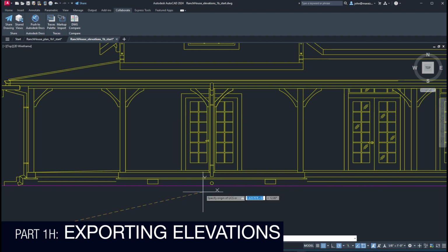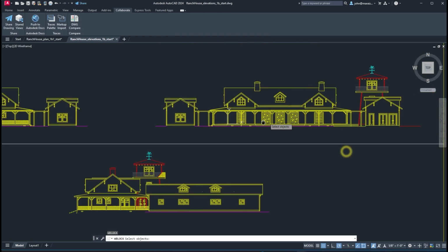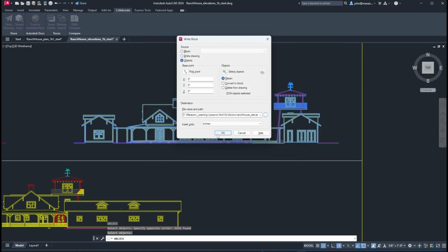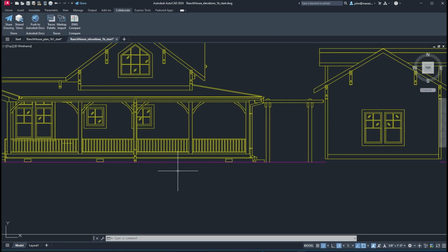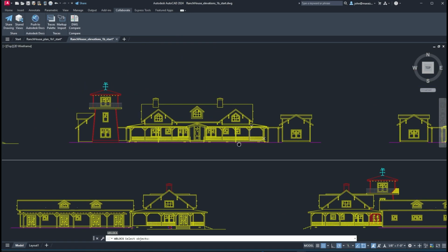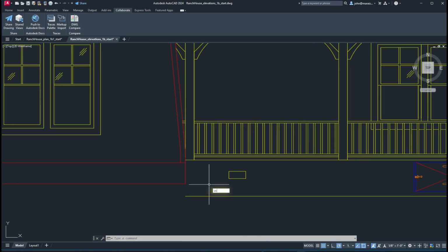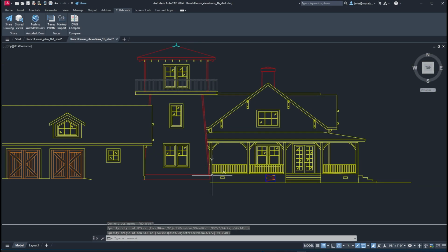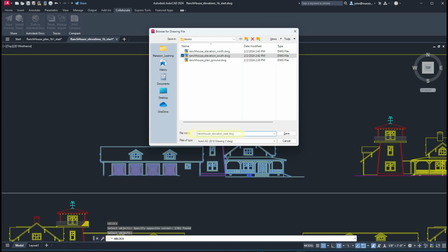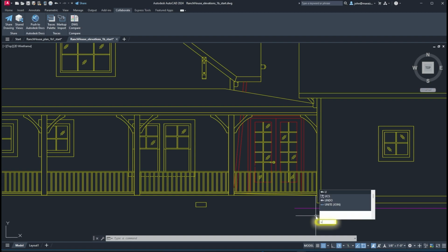Repeat these steps with the elevation drawings, taking care to assign a new UCS consistent with the plan drawing and at the same position relative to the ground plane. I'm using the finished floor level on the main building in this example. These elevation drawings are created on the XY plane in AutoCAD, which is typical. Rather than rotate the UCS tripod before export, we'll simply rotate and position each elevation in 3ds Max.